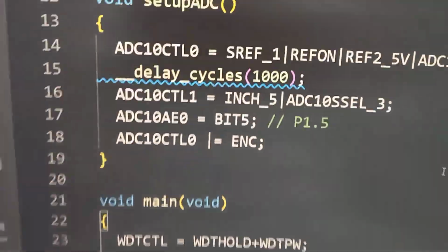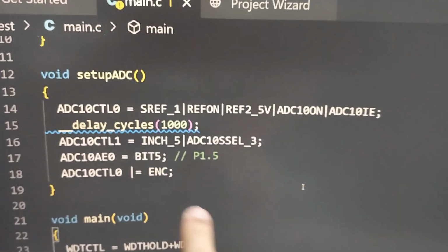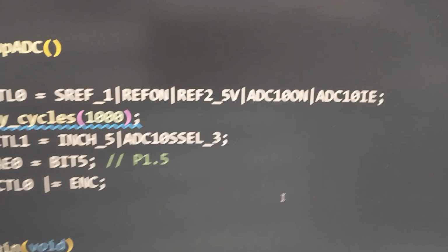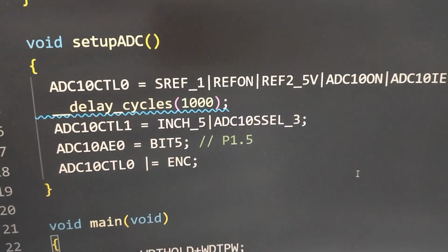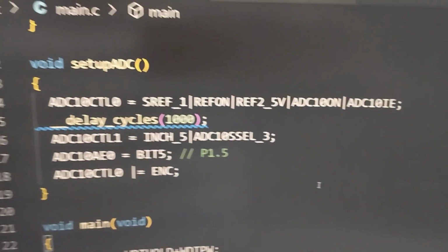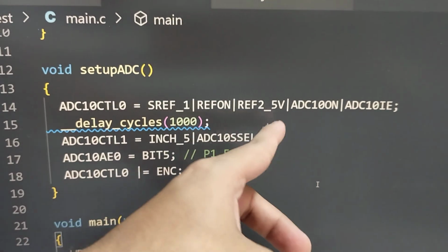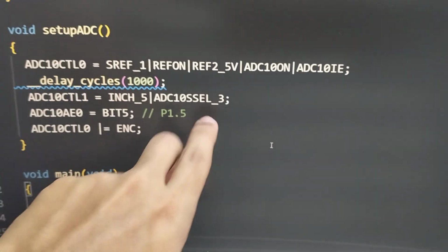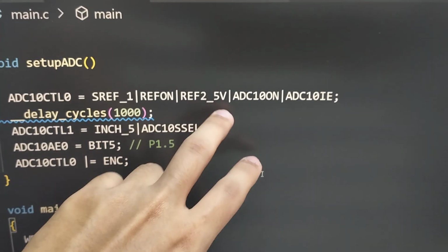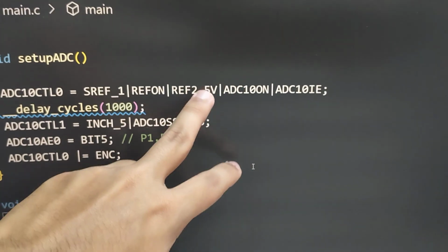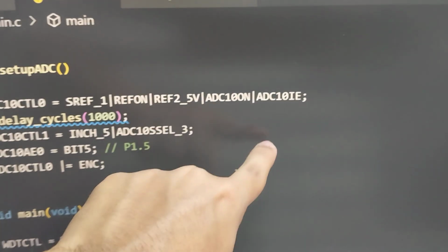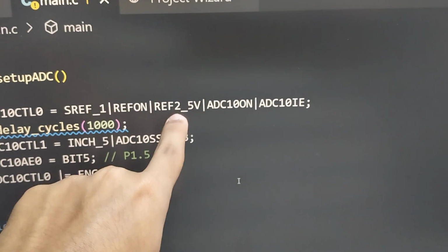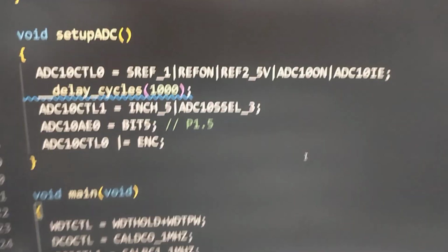And another thing here is we have another function, the ADC, that's basically to set up the entire ADC. As I said, you can choose different references. It's not necessary that you have to use 3.3 volts as your peak. Just like here, for example, I haven't used 3.3, I'm using a 2.5 volt reference, and this exists internally in the MSP. They have this ready, so you can use that. Basically, you can map 1023, which is your maximum value, to 2.5 volts. So that's what I've done.